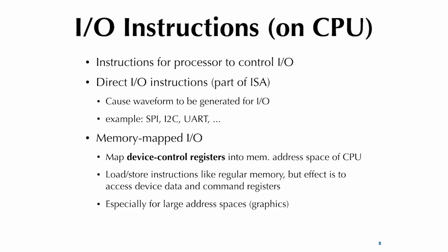So what are I/O instructions? Well, you can do instructions that are part of the instruction set architecture. We've seen in the case of the 8051, you have these move instructions that work with I/O ports. Those are actually I/O instructions, even though mnemonically they look like MOV, they're really different, right? At least if you go to certain spaces, certain numbers, those have special meanings. Those would be called direct I/O, or if you do a move to your general purpose I/O ports, you actually set the bits to 0 or 1.